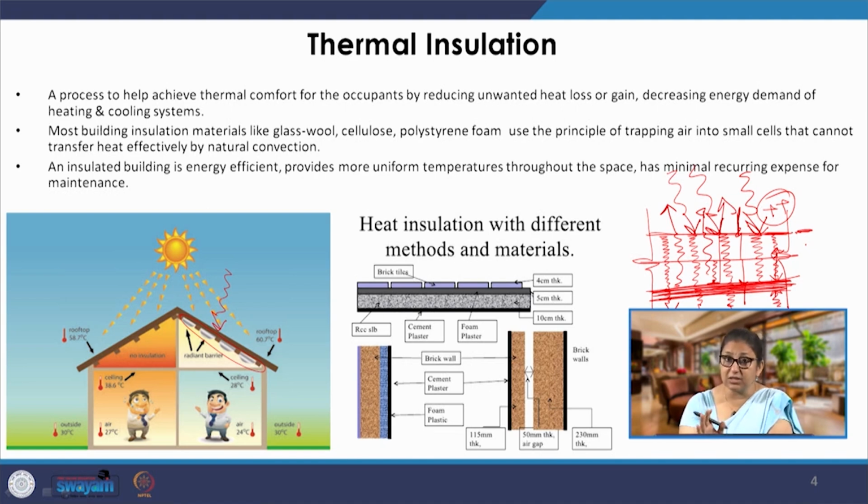For this thermal insulation we have a lot of different materials, whether they are synthetic materials like polystyrene, or materials such as glass wool, rock wool, or mineral wool, which have less density and a lot of air gaps in between, which act as insulators, plus they have very low conductivity due to all these reasons. And that is why the concept of thermal insulation works, but it is always going to be an additional thing. We can also have thermal insulation with the help of air itself.